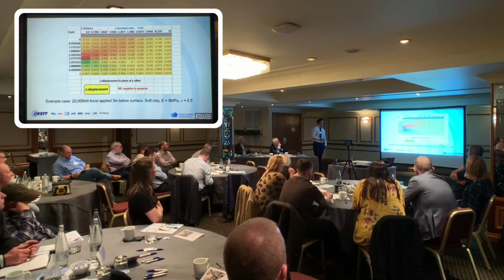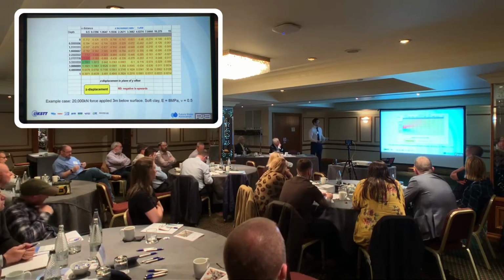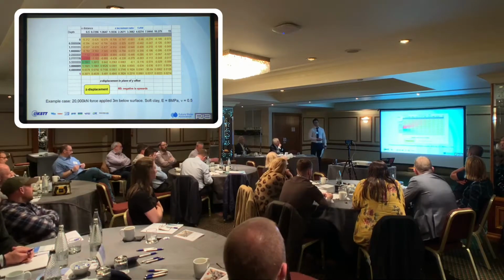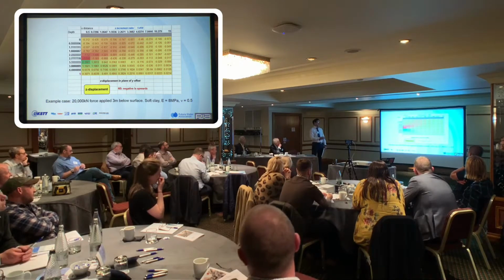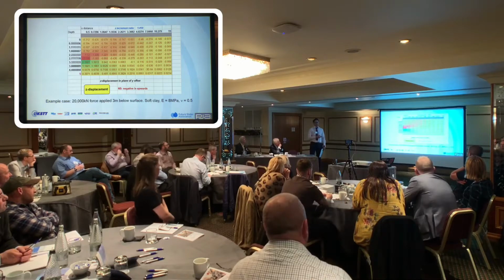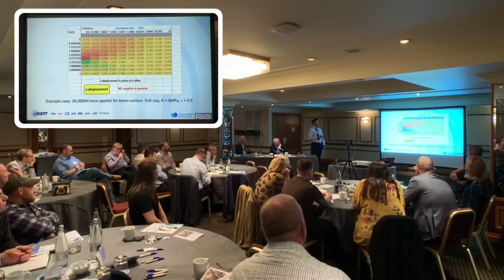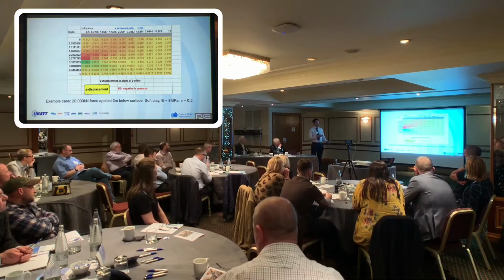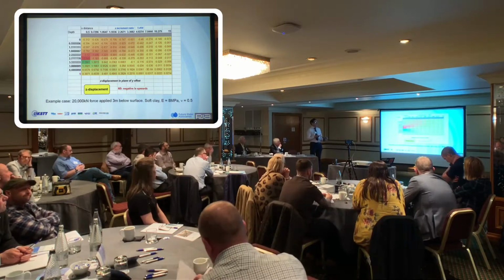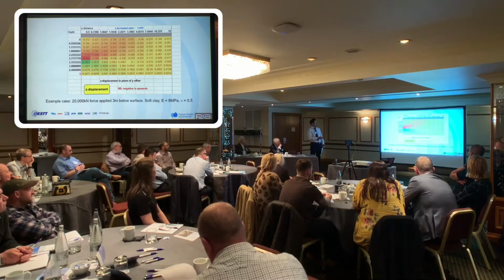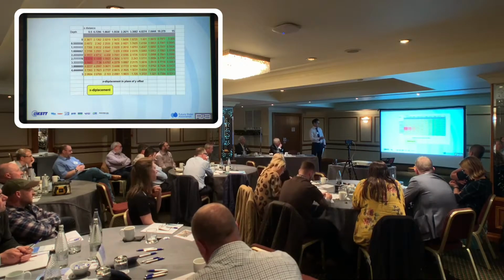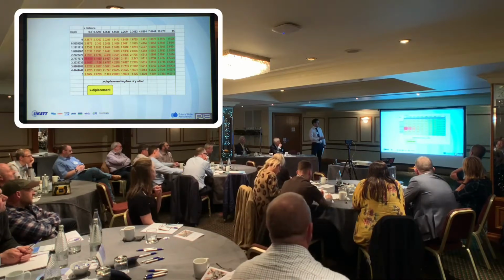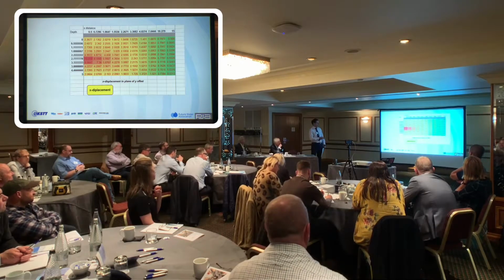As well as the ground profile, ground modelling for the contractor and the shaft construction, these are the other elements we're asked to look at. The heave assessment will give you a limit as to the face pressure. As long as the face pressure is less than the reactive heave amounts are telling you, then it's okay. The final slide again is a further example of where heave can occur.